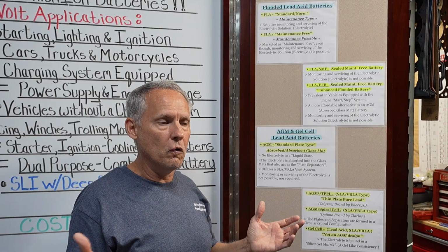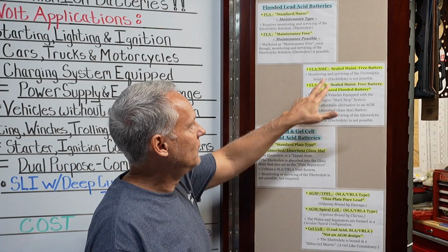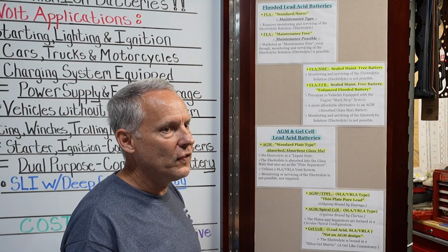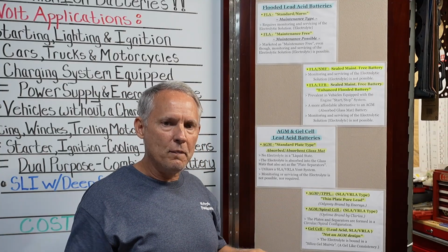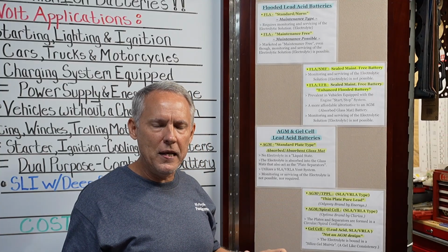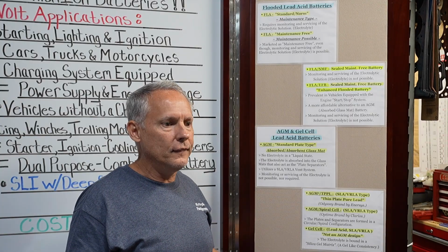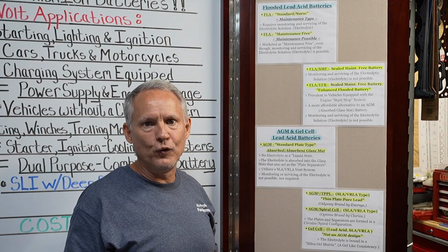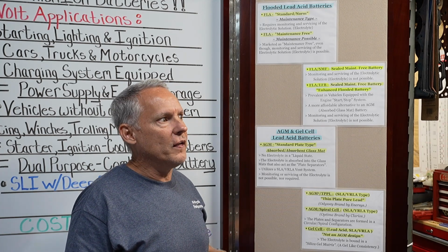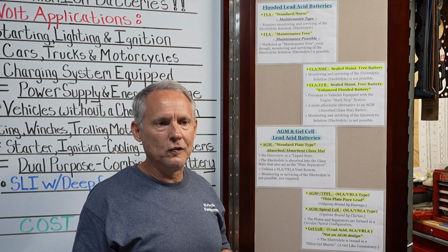Both of them say sealed, but the reality is that a sealed maintenance-free battery is a type of battery where the top of the battery, over where the caps would be, or how you would access the electrolyte, they put a big sticker. Maybe they put a little bit of hot glue on the cap so it can't easily be removed. The reality of it is, it still has electrolytic solution, it still has electrolyte.